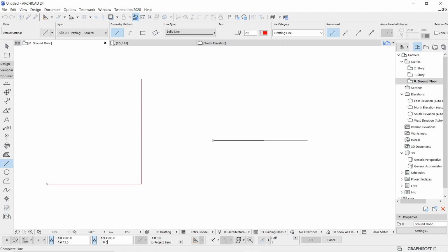And now when I press the enter key, you can see that I've drawn exactly one segment of 4,500. If you want to check that, press M from the keyboard. Now you know it very well. Use the check mark from one end point, pick that point and touch the other point, and you will get the confirmation that you have drawn exactly 4500 as the length of that segment. So now I have used a single escape to terminate the measure tool.